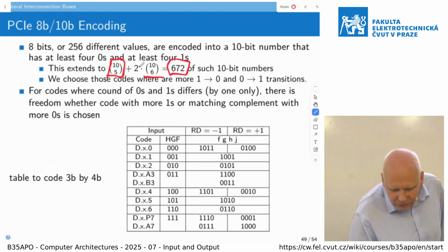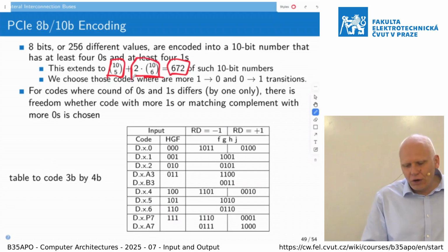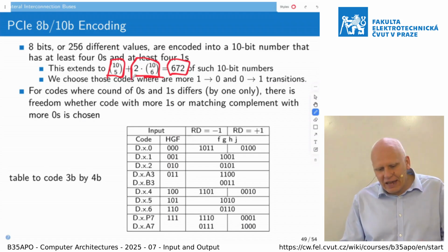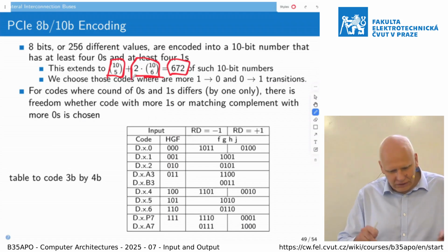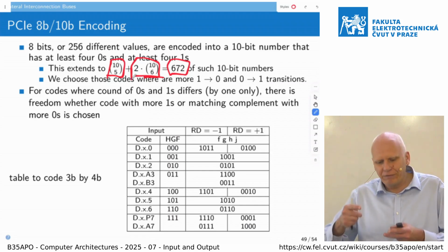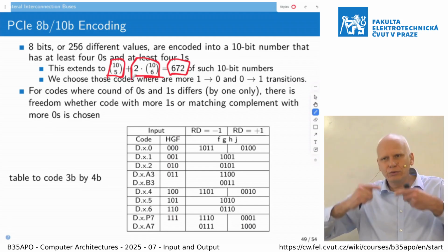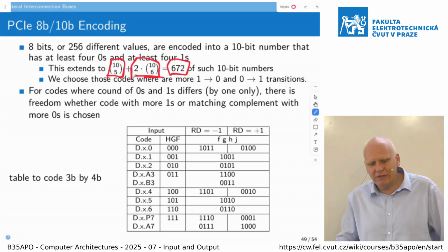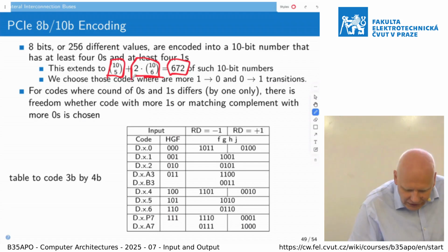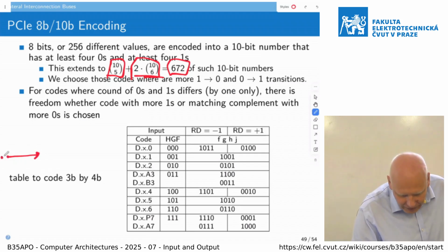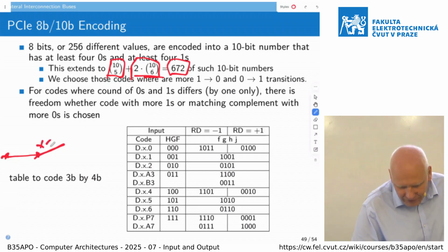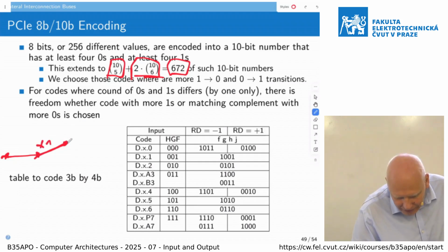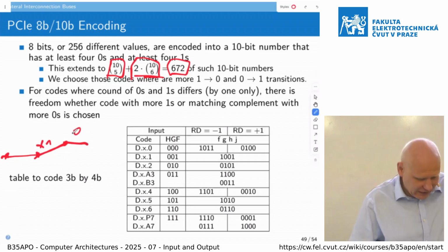But if we take from that second part only 1/2, then we can have those which have 0 difference and those which have positive 1 difference. And then if we use those complementary which have -1 difference between ones and zeros, then we can use such an encoding scheme where we send the data with 0, no problem. Now we send the data which offsets the DC component by +1. Then, for example, next by 0, if such a code comes.